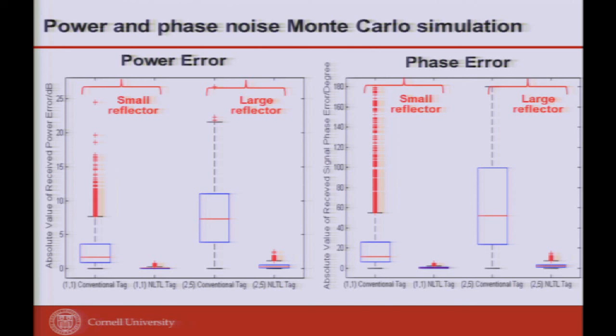This is the box part of things, but you can see that the worst case is bad. There are some reflectors and some arrangements of the reflectors that can give you large phase, amplitude or power errors. In phase, it's even more clear. On average, it's not bad. Reflectors in the fundamental multipath on average look like only 15 degrees phase errors caused by many of the reflectors. But the worst case can be 180 degrees. That means the phase is no use.